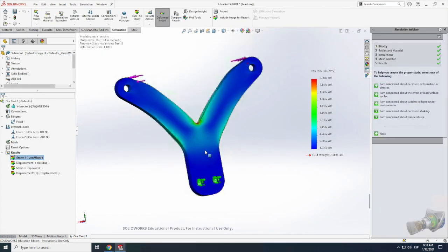Alright folks, we are back again in here. It turns out that Solidworks crashed, so I had to redo the simulation all over again. But it's essentially the same thing, the same numbers that we had before. I just realized that we can see the deformation scale in there, which is 1102.5, which is a lot, and it's very representative of the numbers that we've seen. So as you can see, we got all of these blue regions, as I was mentioning earlier. We want to see whether we can remove them or make something more optimal out of here.